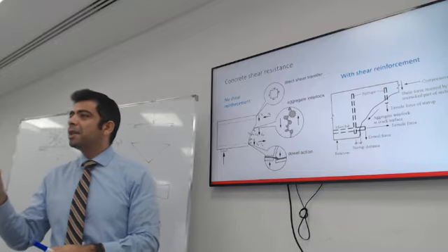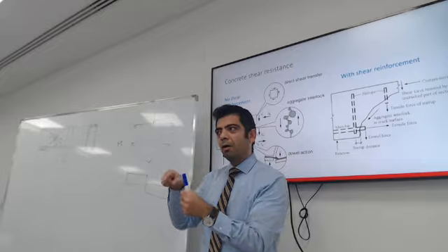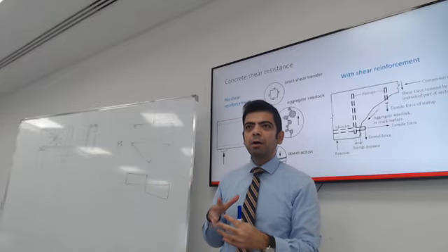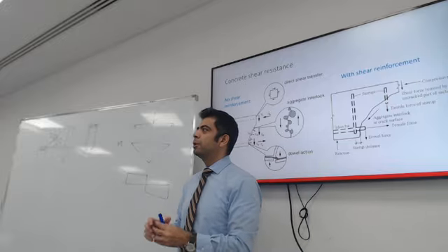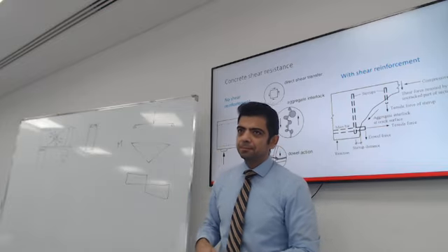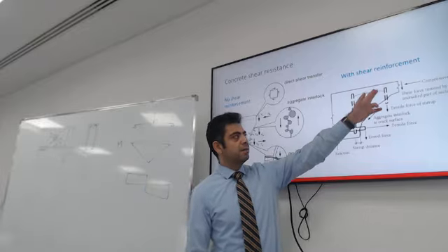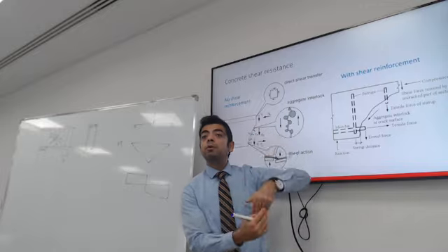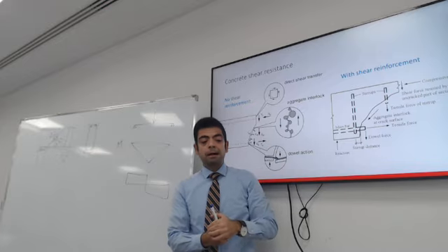So can I get you to guess, what if the area of the stirrup is not enough? I need more steel in the stirrup. What are the options? I'm curious if you can figure out what you need to do if we need more steel area out of the stirrup or the links. This will help take the tensile load to close the crack, or to stitch the top and bottom pieces together.